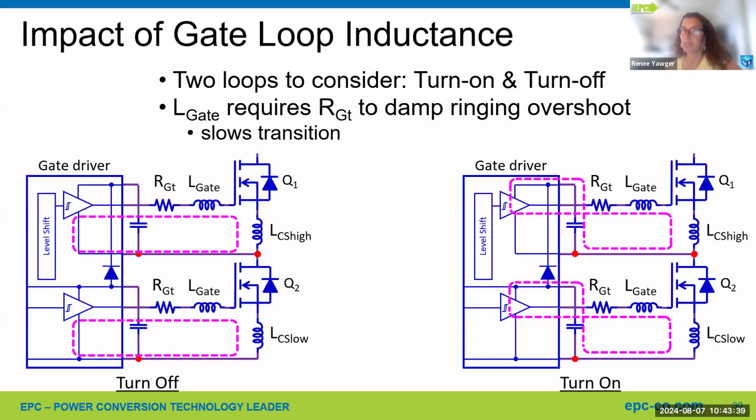Okay. EPC power stages are rated in amperes. Typically, they are top driver. So, like the EPC23101 is rated to 65 amps. How is the current rating specified? Is it the RMS current on the top FET or the output current on the converter, like a buck? Yeah, it's the output. It's like a guidance. As these get into production, there'll be more specs as far as FET by FET. But the short answer is it's output based on a few things, based on the current capability of the internals, based on thermal limitations and so forth.